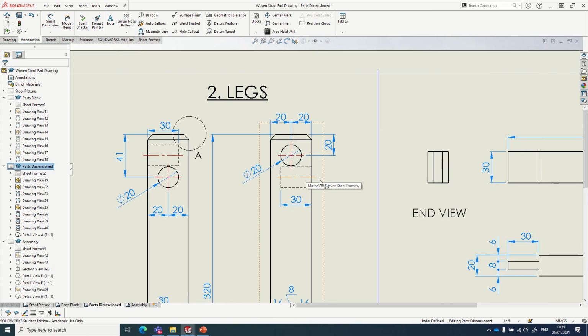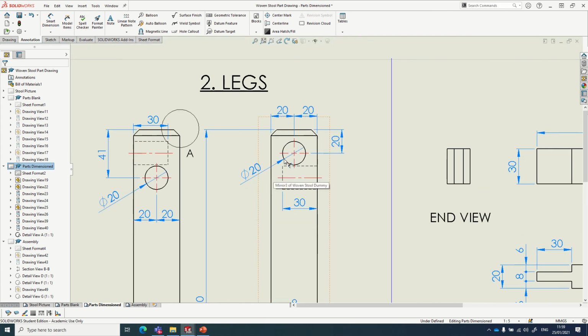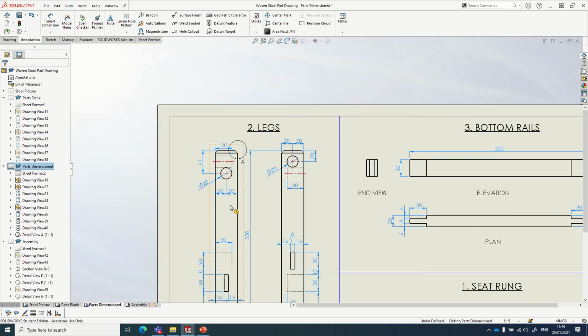You can see our dimensioning standards then, with our long, thin arrowhead like so. We can see the text placement sitting upright or to the left-hand side of the piece. Wherever we have, say, a hole that's to be drilled, we put in our diameter rather than our radius. And all the tips that we gave in our previous videos about how to dimension, what's important about our dimensioning, would apply here.